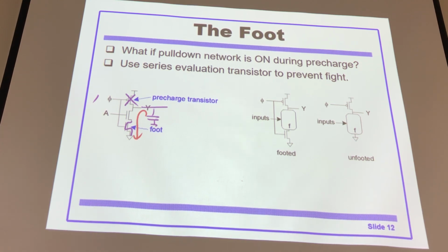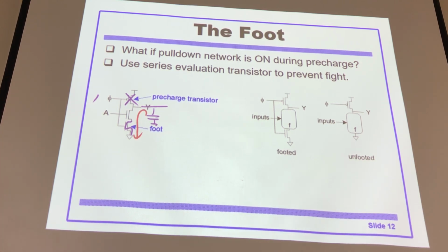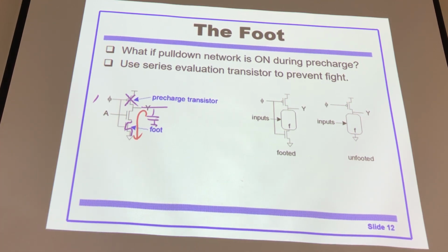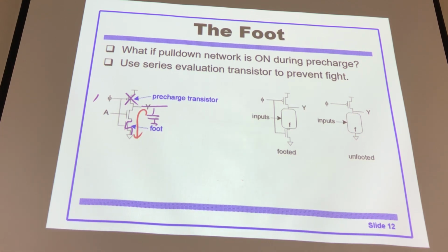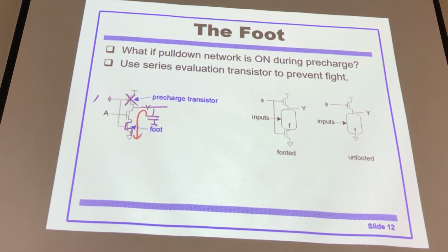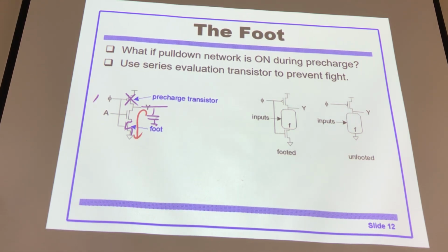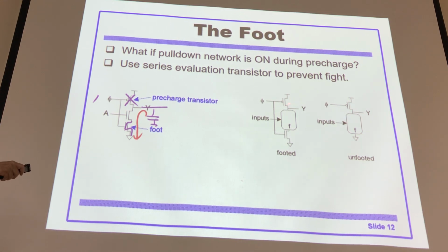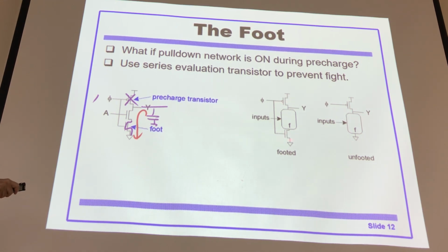So how does it compare with static CMOS? We know that static CMOS is better than pseudo-NMOS. How about the dynamic circuit here? Anything better than static CMOS? We know that this is actually the same circuit as static CMOS in the pull-down network. For the pull-up, you need only one PMOS transistor, and you also need one NMOS transistor at the bottom for the foot.